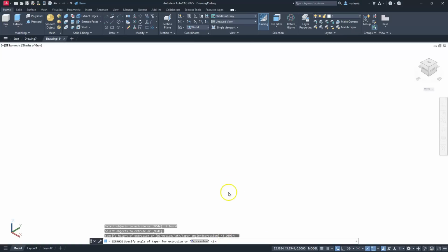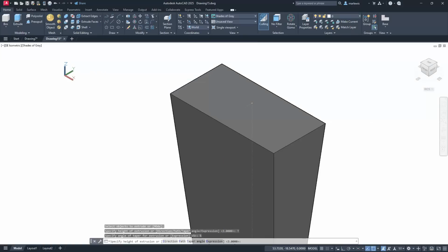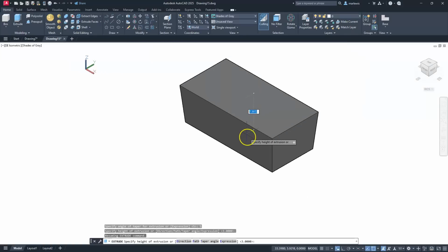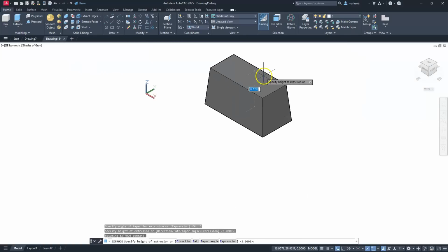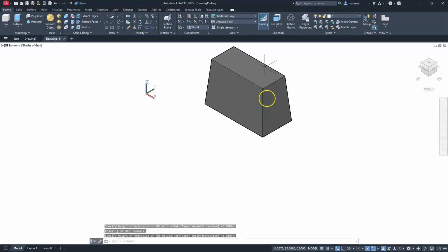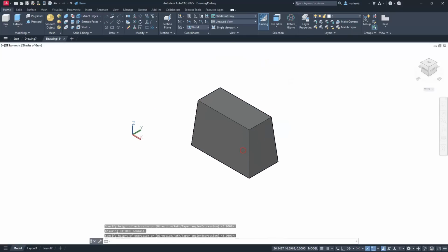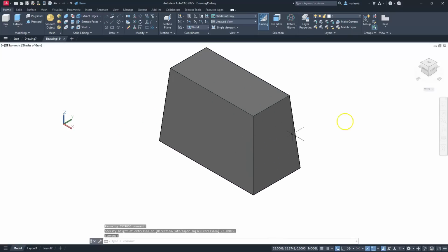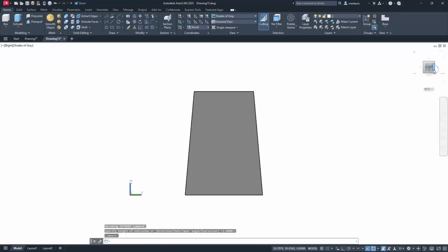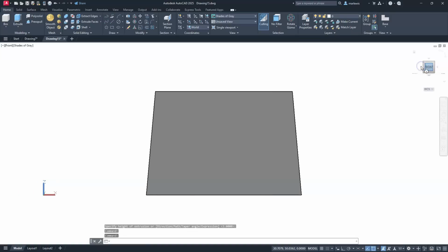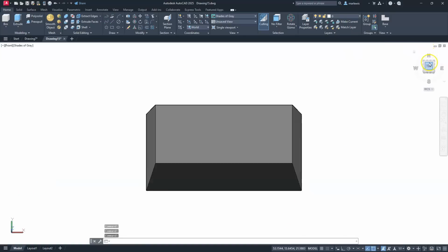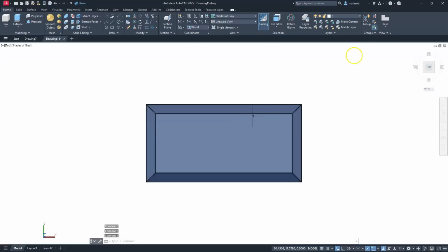degrees. And now you're going to see that when I'm creating my part here, as I'm going up and down, it's going to have a tapered angle on the inside, right? Let's go ahead and click here. And then what I want you to do is take a look at this on the right side, front side, and you can see all of those tapered angles, right? Especially if we look at it from the top view here, you can see it going all the way around.